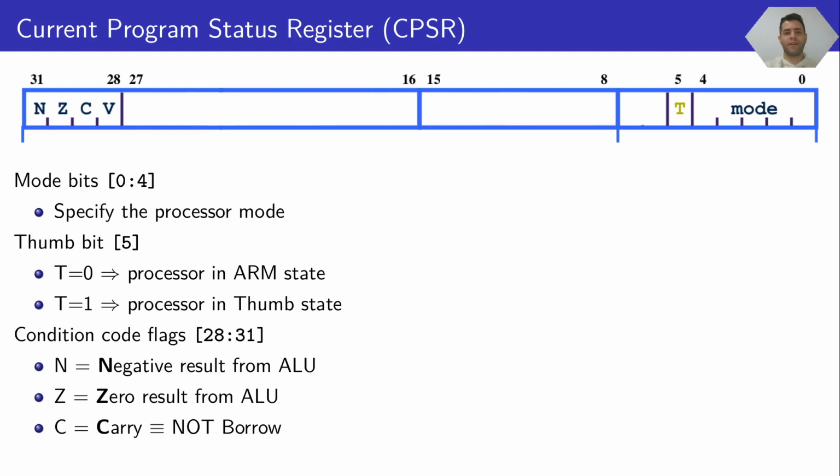On the other hand, if you are subtracting and the carry flag is set to 1, it means that the borrow flag is set to 0, and it means that it's fine, it's good. On the other hand, if you were subtracting but the carry flag is not set, it means that you needed a borrow, and this is something bad. We will see a table in a couple of seconds.